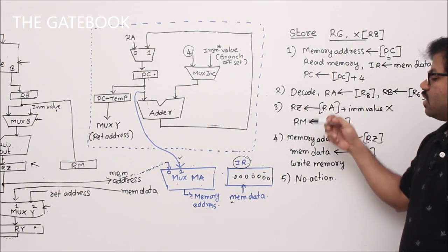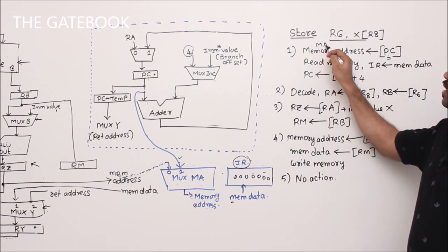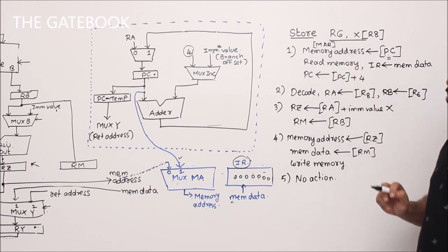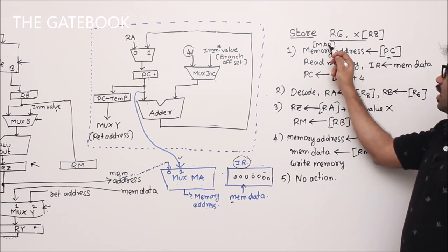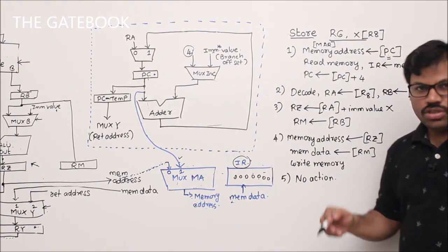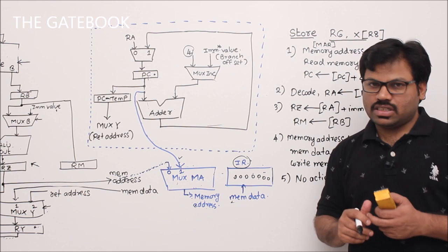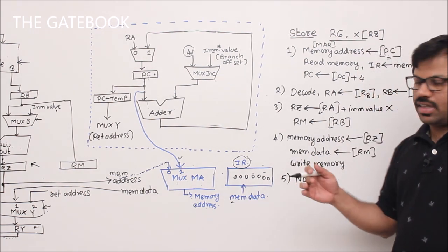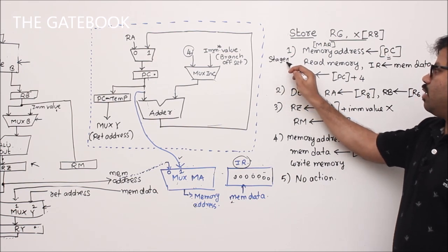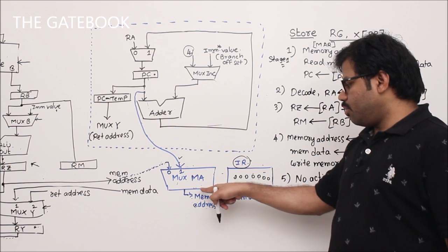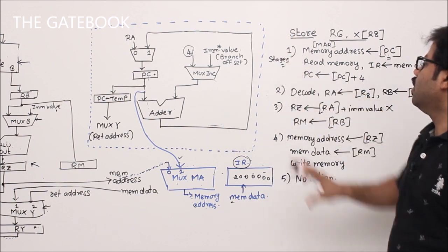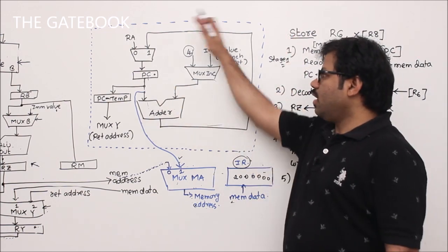So again assume that there is a memory address register. You might assume like that, but that is not compulsory. It's implementation dependent. So assume that there is a memory address register, and you are sending the program counter's address to it. Once you send it, automatically the memory interface will start working and it will give the data. Already I explained that, right? So stage 1 is pretty clear, correct? In stage 1, the program counter address will come here, memory will start working and it will give the data back to the instruction register in 1 clock cycle. The program counter will be automatically incremented in parallel.